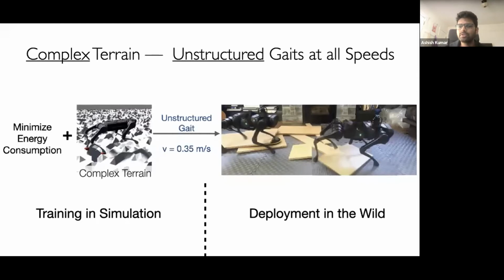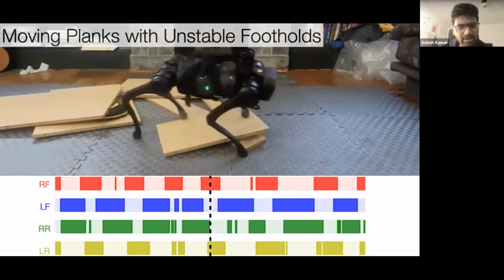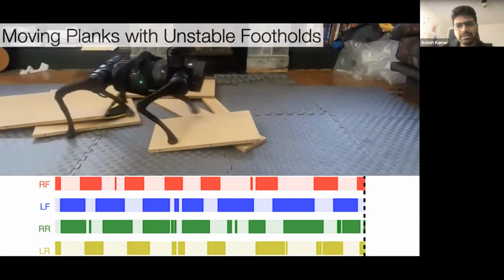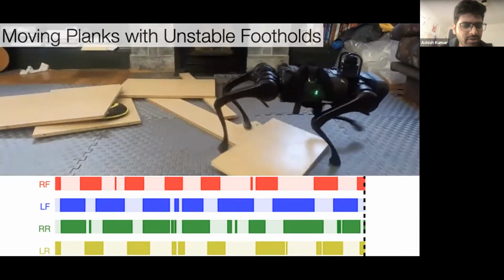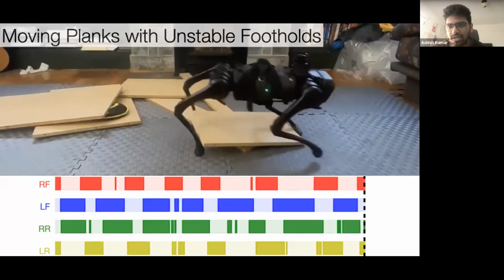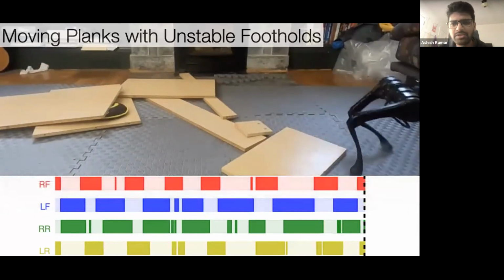And now what we are going to do is deploy it in the wild. Now we make it run across this sequence of planks, and we will observe, and I'll plot the gait just below it. The dark color means that the foot is in contact, and the light color means that it is not. And we will observe that it is not following any specific gait every time it comes next to an obstacle. So the gait patterns are very frequently violated in this region, every time it faces something which is not flat.